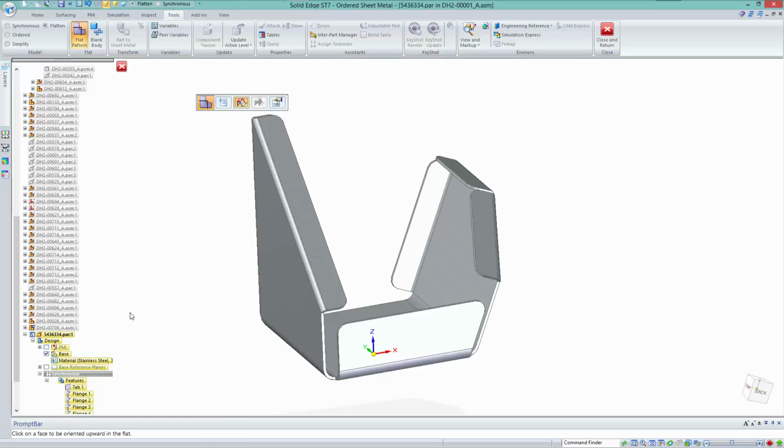I can then follow the prompts and use the couple of buttons here. Again, this is a standard function in Solid Edge for running commands: as soon as this little bar pops up, there's an options page that you can use in sheet metal files, typically for controlling bend relief and corner relief, things like that. But what this bar is showing me is that this flat pattern tool is a 2-step process.